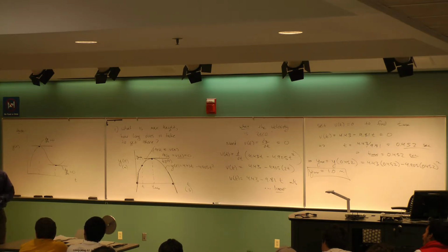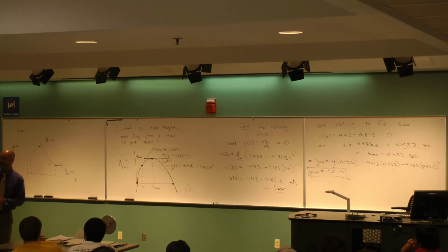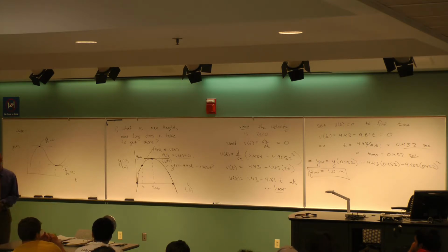All right, so here's the thing. This is interesting. We got biomedical engineers in the room, right? Is acceleration the thing that actually damages the human body? What damages anything? Force. More importantly, force distributed over area, right? Your femur can take a lot more force than your phalanges. So bottom line is, it depends how big it is, but force acting over a certain area is called stress. That's what breaks things, right? Whether or not this thing smashes when it hits the ground, it's the impact force that controls that.